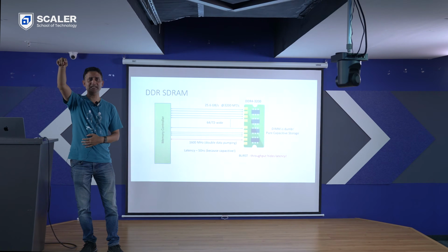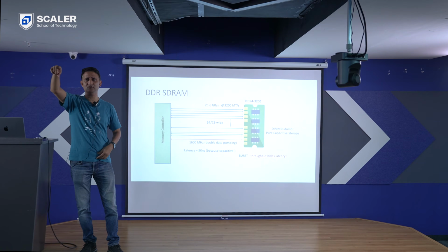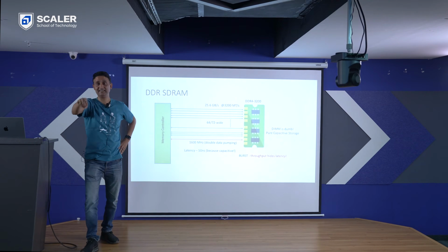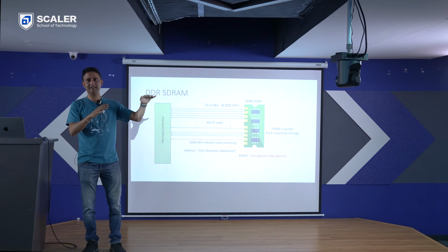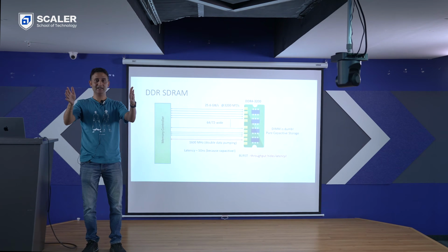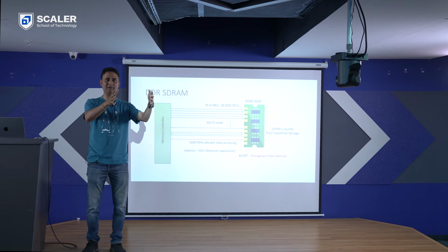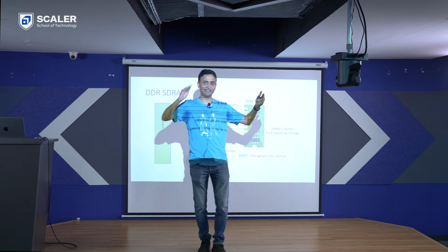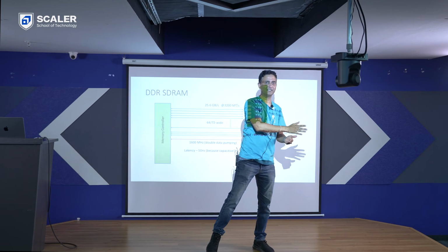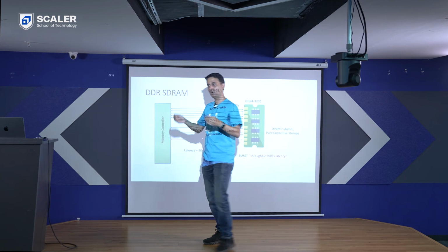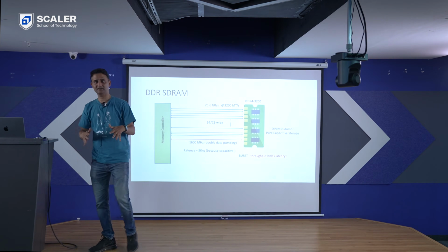Sometime earlier we were talking about latency being 13 nanosecond or something, or 15 nanosecond, right? Yeah, 15 nanosecond. That latency, DRAM read, is actually a multi-stage process. Some of the earlier stages take up a fair amount of time. Once those steps have been done, sequentially I can keep firing a bunch of additional read requests up to a limit. Okay? All of those things I can send out as a burst.